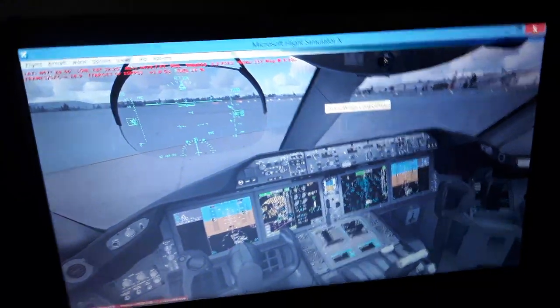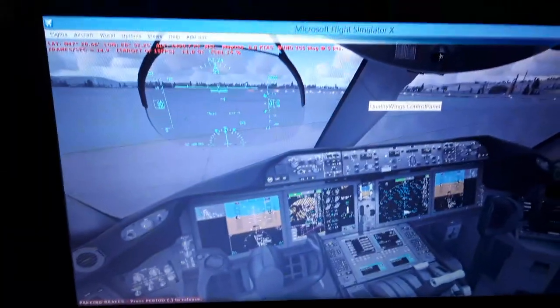So now continue with the navigation display, which displays the GPS position of the aircraft, the terrain, weather reflections from the weather radar, and the terrain map with the airports. You can see the airport where we are located right now, Zurich International Airport, LSZH, and the runway we're going to use for takeoff and for landing, the same runway, 14 at LSZH airport, and the same LSZH localizer for takeoff and for landing. We're going to have the same frequency tuned in the flight management computer, and the receivers are going to give us the LSZH localizer guidance.